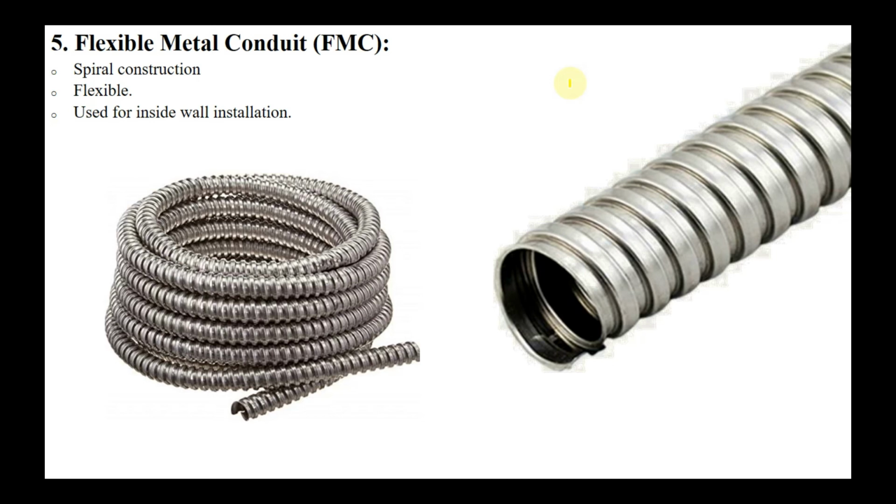For that suspension, we use FMC because it has a spiral construction and it is flexible. So when there is some sort of hanging or suspension, we use FMC. But FMC obviously can be used in some other scenarios which fulfill this criteria.